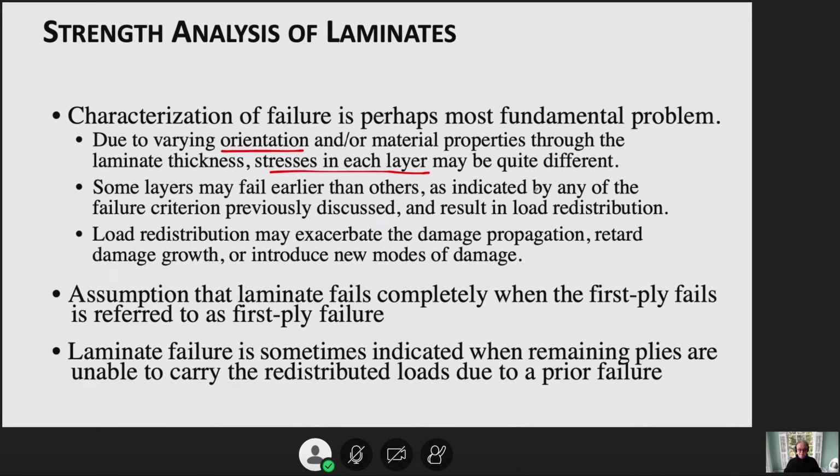If we consider an in-plane problem, no bending, then strains epsilon x, epsilon y, and gamma xy are the same in each layer, but they are not necessarily the same along different fiber orientation layers. So you still find different orientation strains along different orientation layers, but at least stresses in the x, y directions are the same.